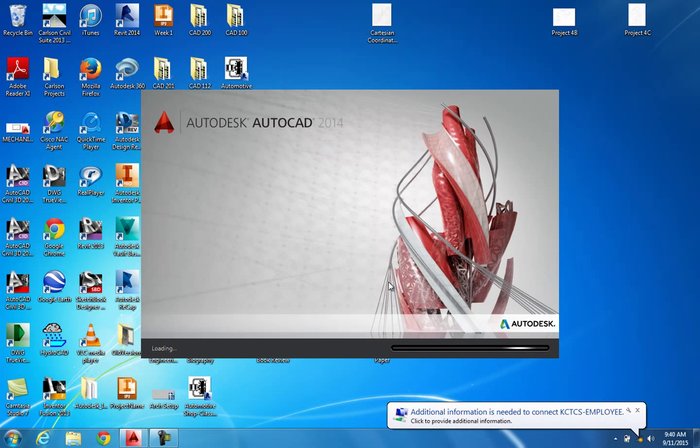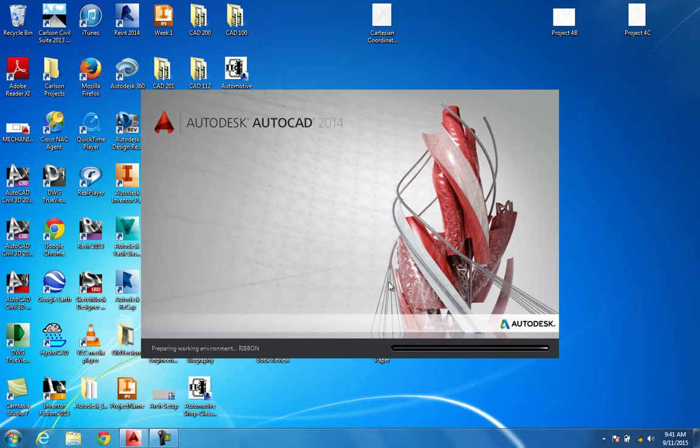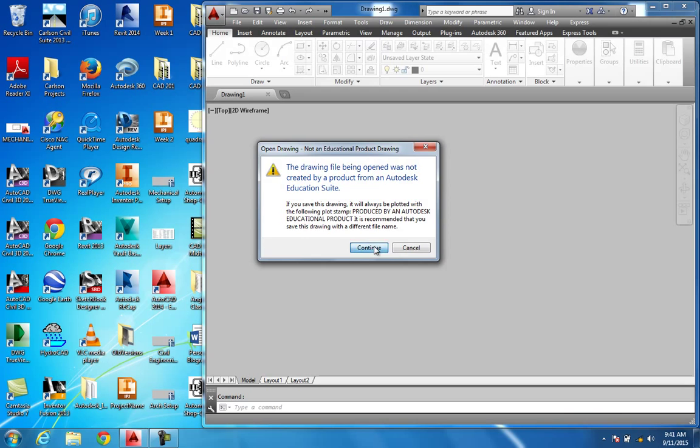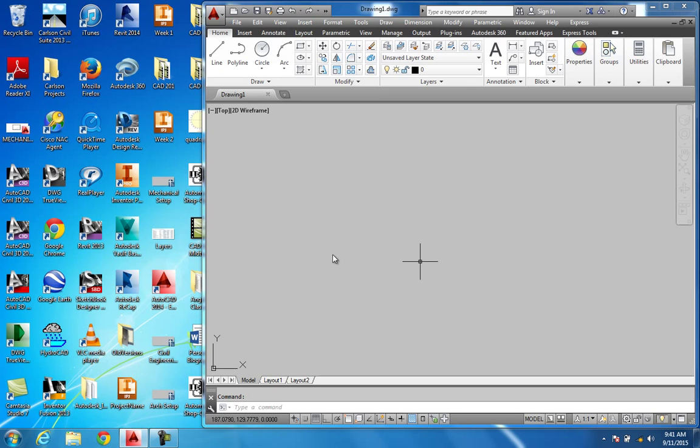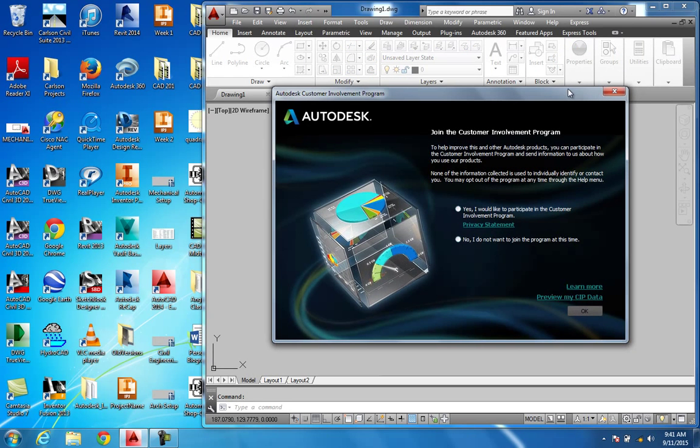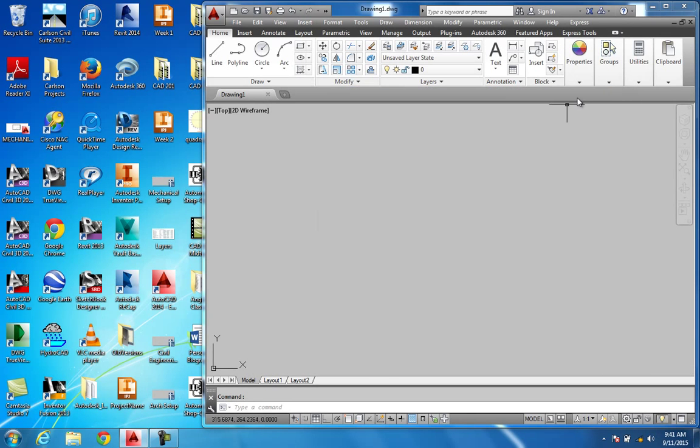And it goes ahead and opens up AutoCAD for you. Then it reboots its memory, its system. It takes that imperial feet and inches, removes it, and puts the metric system in. So you'll notice it comes in to a normal AutoCAD screen just like this when it gets loaded up, and you'll be ready to start drawing.